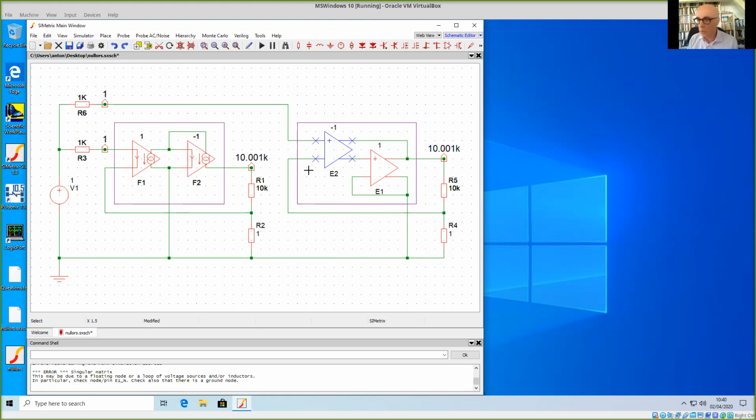A 0 is 0. So the only thing we want to be sure of, if we implement the controller with a thing that has a finite gain, is that the loop gain is negative, because then we can speak of corrective feedback, and an error will be corrected such that it converges to a stable output.